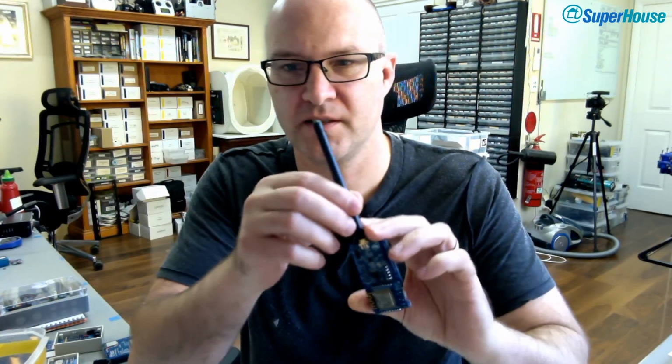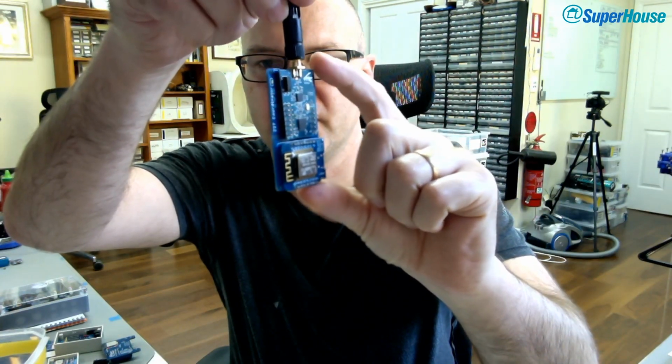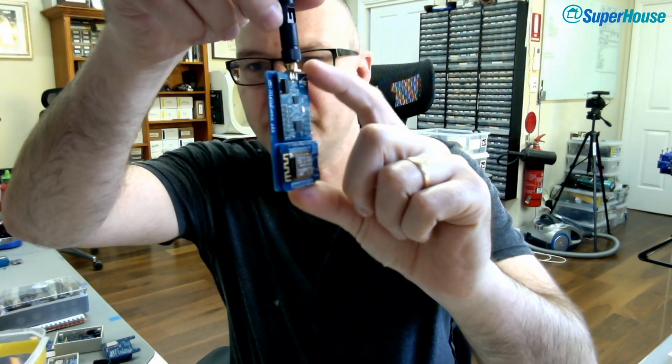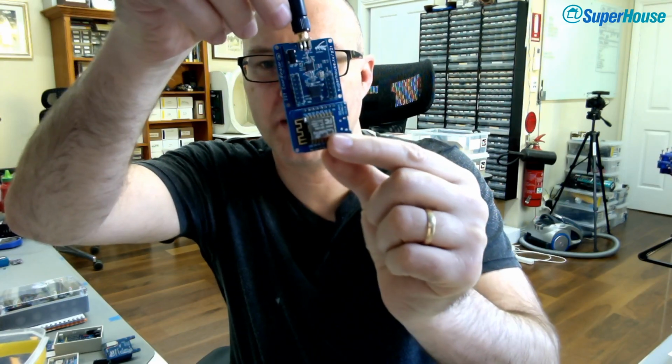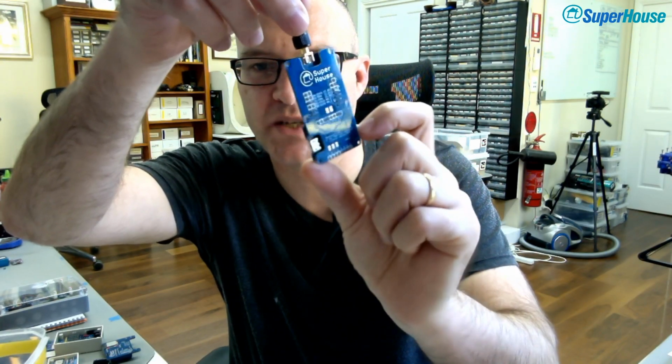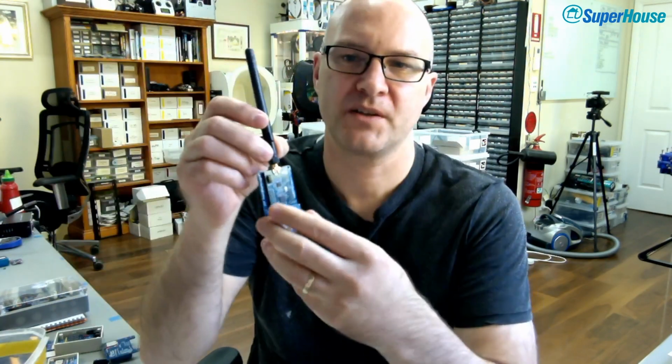Actually, I'm going to unplug it, which is going to kill my Zigbee to MQTT. And what you can see on here is there is a Zigbee module, this is a version with an amplifier on it, so it's quite sensitive. And then there is a Wemos D1 Mini, and it's all sitting on a little PCB that I designed. What this does is receive Zigbee messages, and then they are processed by Zigbee to Tasmota running on the D1 Mini, which then pushes those messages to MQTT.